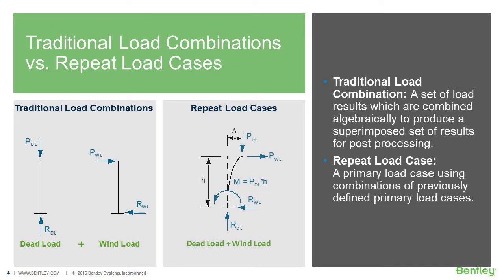Now, I know some of the topics we're going to be doing today are probably fairly familiar to a good portion of you, especially if you are experienced STAAD.Pro users. You've already probably generated load combinations or at least created a load combination in the STAAD.Pro Analytical Modeler. But whenever I personally discuss load combinations, I like to start with the basics and talk about the difference between traditional load combinations and repeat load cases, as this could have a significant effect on your analysis and eventually your design. And of course, you're going to have to think about your code requirements when generating any load combinations in STAAD.Pro.